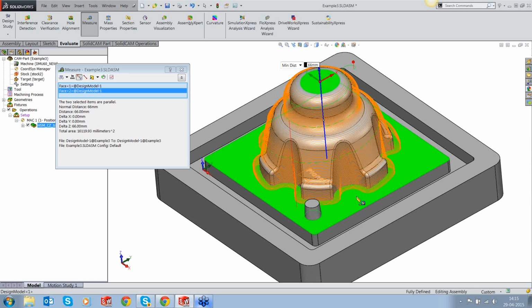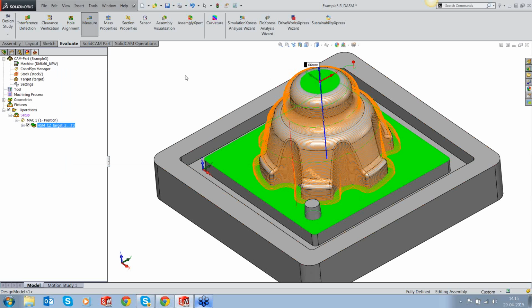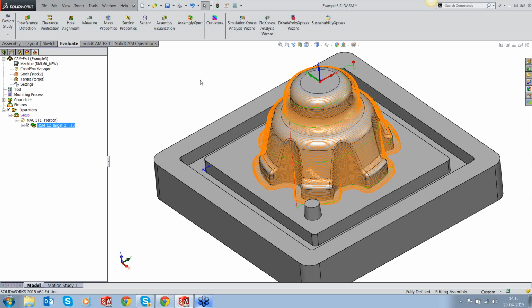which means that a lot of vibration and chatter would be induced, because your L by D ratio is going to be higher. If you're, let's say, using a 10 ball nose cutter, your L by D ratio is going to be about 6. Now, what is the other best way? If you have a 5-axis machine, obviously you could generate a 5-axis toolpath. But generating a 5-axis toolpath on so many surfaces is actually a big job.